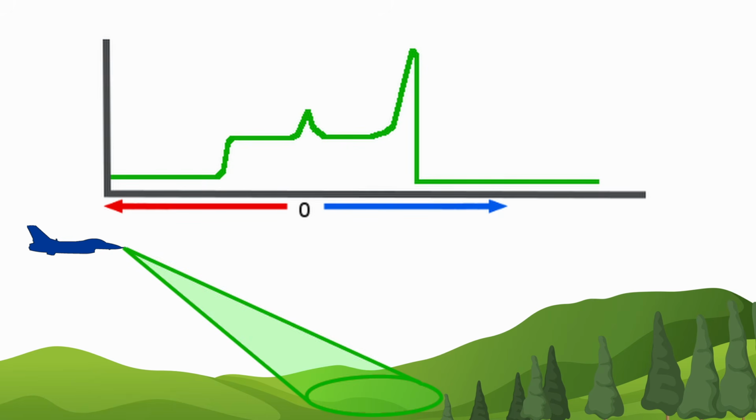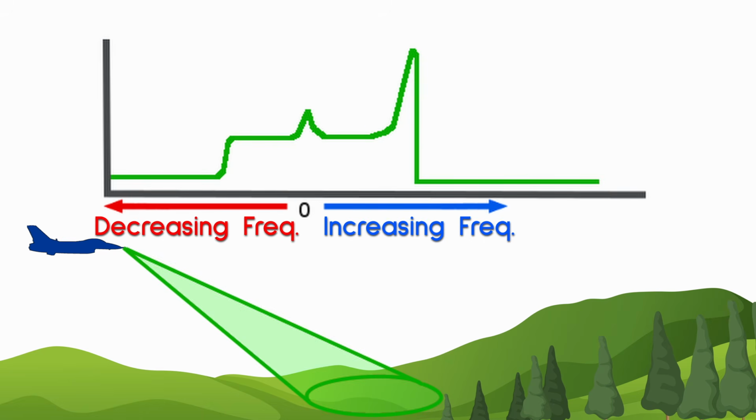on an aircraft. This big spike is from the main lobe of our radar reflecting off of ground clutter. It's at a higher frequency than what's being transmitted. This is because the aircraft's forward movement is introducing closure with the terrain. So the spike will always be at the aircraft's velocity relative to the terrain. In other words, it will move outward as you speed up and come closer as you slow down. All this back here is ground clutter returns from the side lobes. This includes some rearward-facing side lobes, which is why we have negative frequency returns.